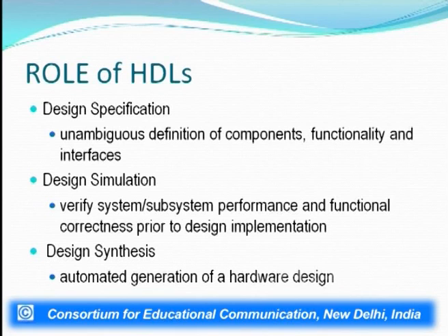Now, talking about HDLs, what role does an HDL specifically play? The role can be divided into three parts. It is used for design specification, design simulation and design synthesis. By design specification, we mean that an unambiguous definition of components, functionality and interfaces can be given. That is, what is exactly expected, what are the components to be used, the functionality that is expected of the circuit and the interfaces that can be employed in this particular circuit.